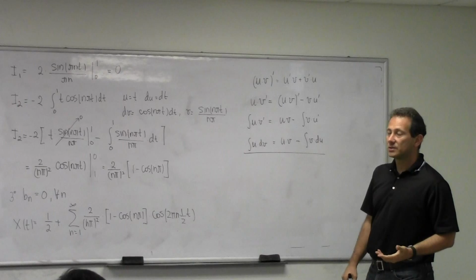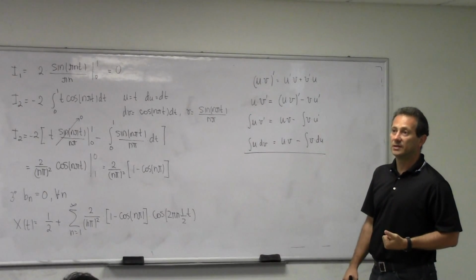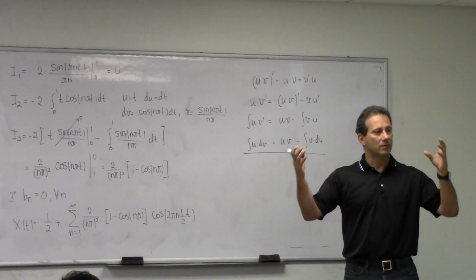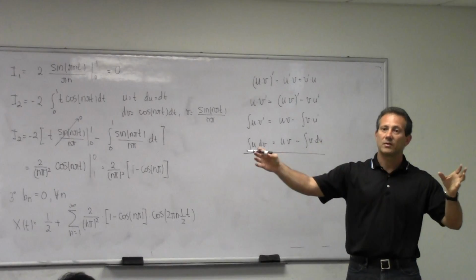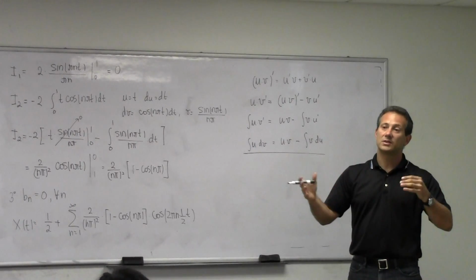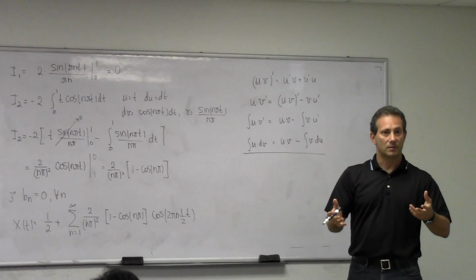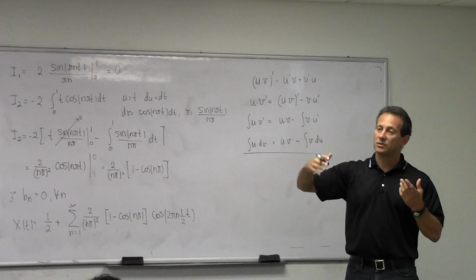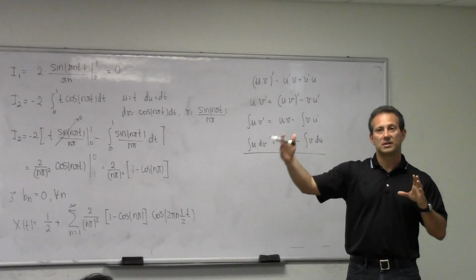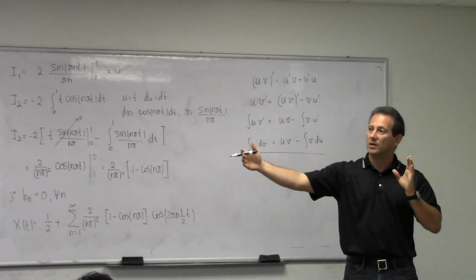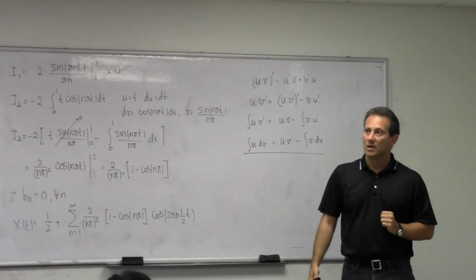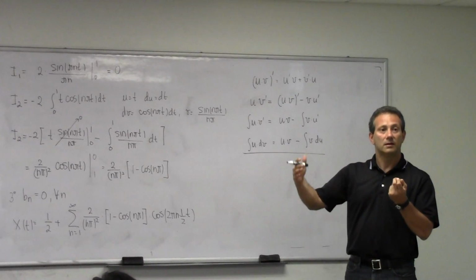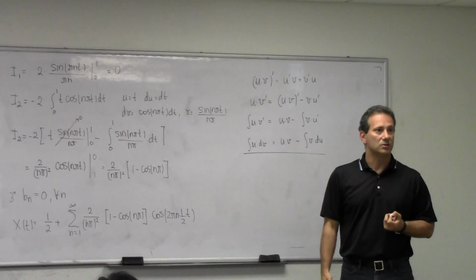Now, a frequently asked question is, how do I determine the number of components that I need to represent this signal? Remember the way we see a periodic waveform when we put on Fourier series glasses, we have it built out of harmonics, right? Each of these harmonics carries a certain percentage of the overall signal power, right? At some point, the higher order harmonics are going to have so little of the power that it's not worth even considering, right? And we usually set a threshold. We say, well, up to what frequency do I need to go to capture a certain amount of power? So to perform that analysis, we first determine the signal power directly, and then add components until we reach a certain percentage of that power.